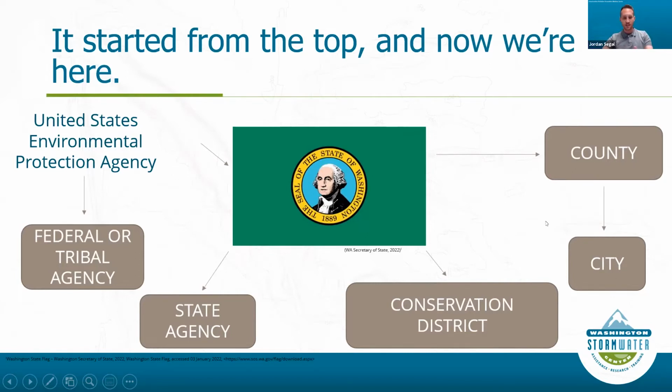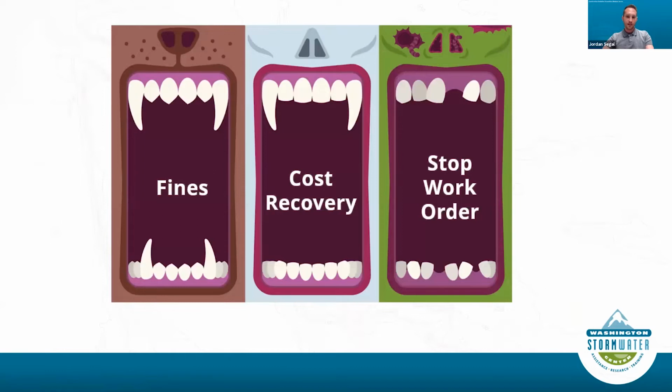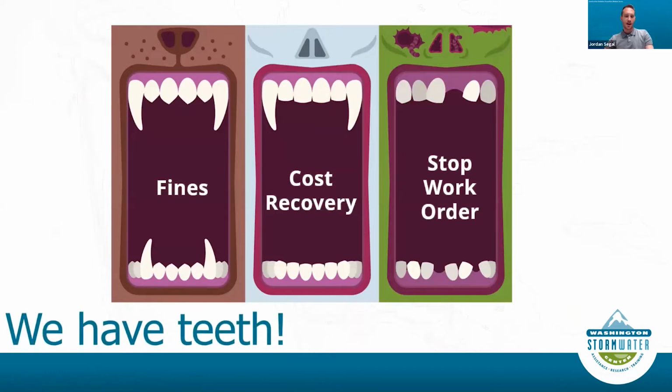And it's important to consider sometimes all of these different stakeholders that might be involved in your project and what rules and regulations they may have for erosion sediment control. And finally, why your project needs to care is that even little guys like the city of Kirkland, where I work, we have the ability to institute fines, cost recovery, and potentially stop work orders if your construction site is not following the correct best management practices to control for stormwater.